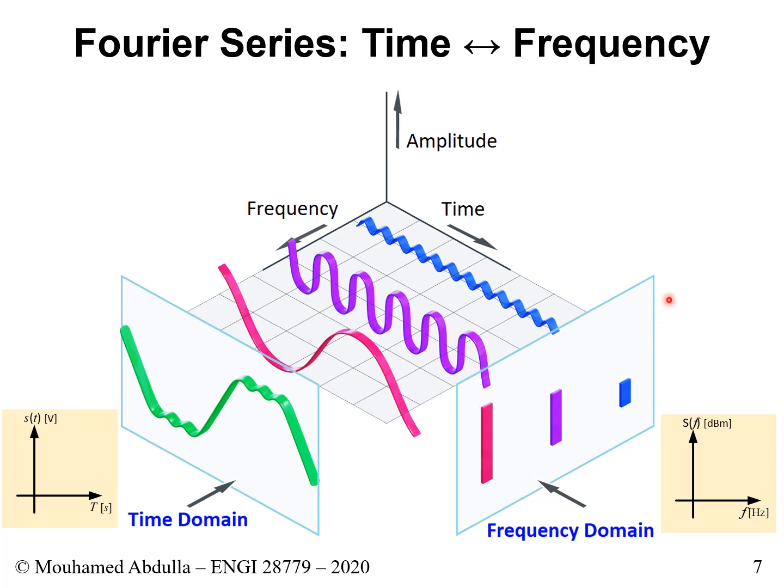So how do you get this thing here? This thing here, the frequency domain. Well, first of all, you break it into small pieces. This signal, you try to break it into different frequencies, operating with different voltages. So with F naught, you have a small contribution. With 2F naught, you have this contribution. With 3F naught, you have this contribution. And if you add all of them together, you should get back to this one, right? So this is the sum of all these different contributions.